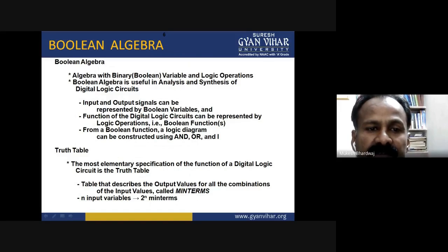Electrical signals such as voltage or current exist throughout the digital system in either one of two recognizable values, except during transition. The switching function can be expressed with Boolean equations, truth tables, logic diagrams, and K-map. Truth tables offer an easy means of representing any switching function of n variables. The transformation of an equation to a truth table or K-map is a little difficult. However, the reverse process of finding an equation from tables and maps requires min term, max term, and simplification methods.